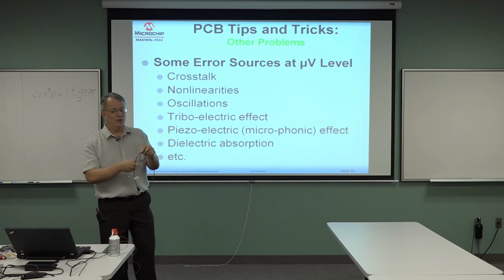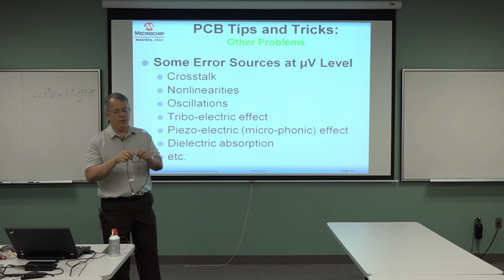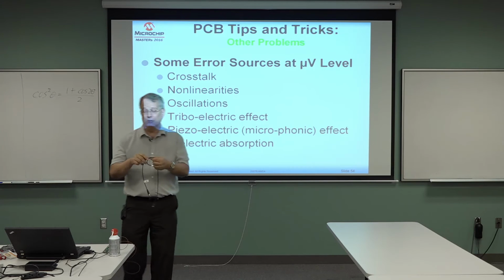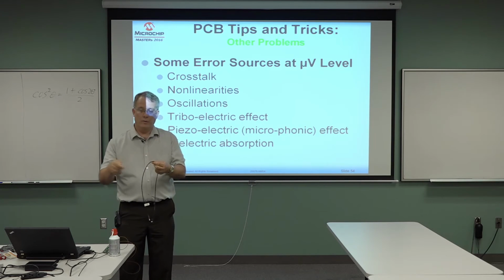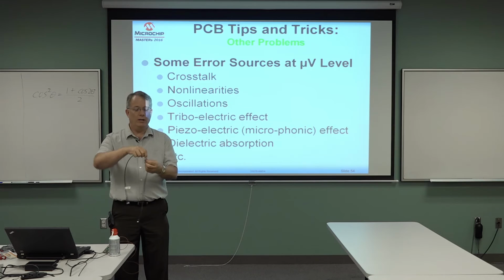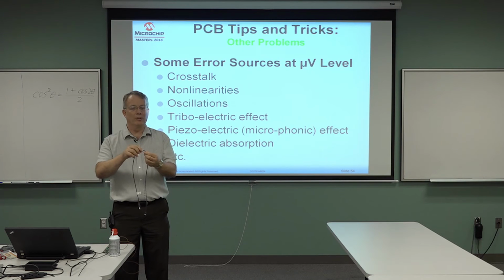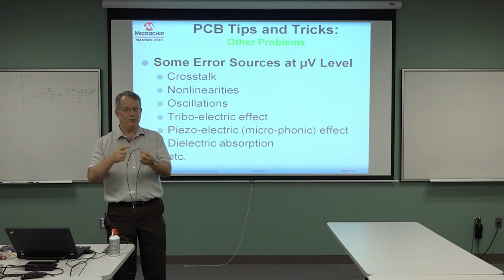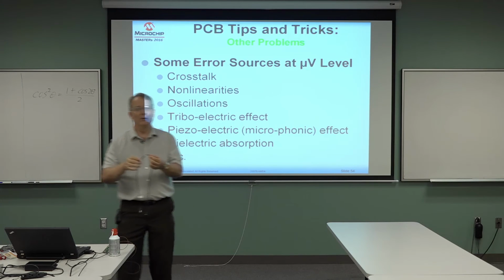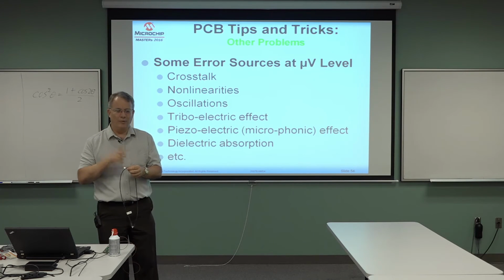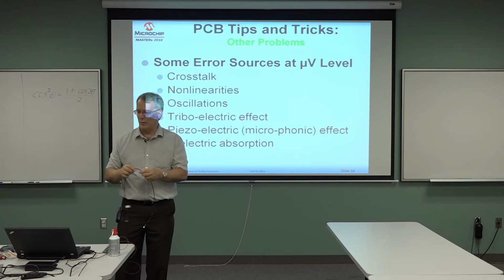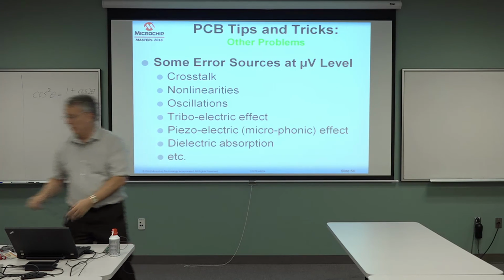As soon as you have a collection of charges somewhere on this cable, that causes a DC offset voltage. So the simple thing to take away is, I had a technician years ago that just loved pretty wiring. And so when he wired our boards to our equipment, he would literally take my coax cables and turn them at right angles, literally right angles. He'd bend them so sharp that they looked square and caused us no end of grief. Not only did it cause this effect, but it also damaged the cable and created a reflection at microwave frequencies. It was just really bad. So the message is that can be a problem.